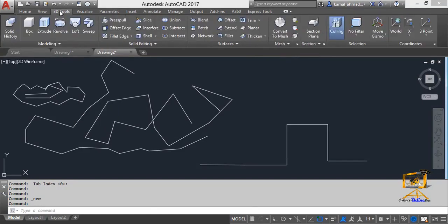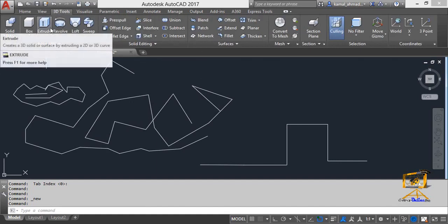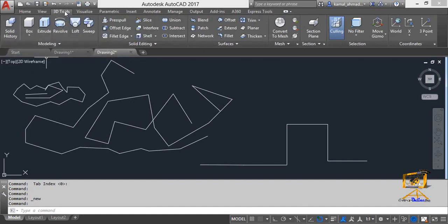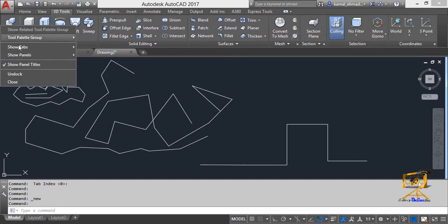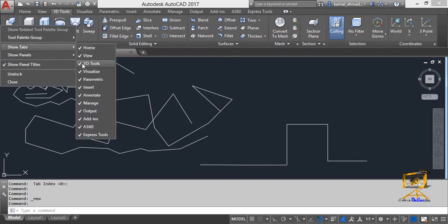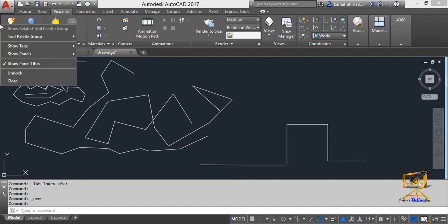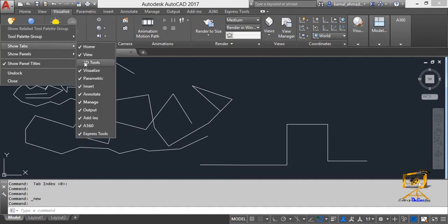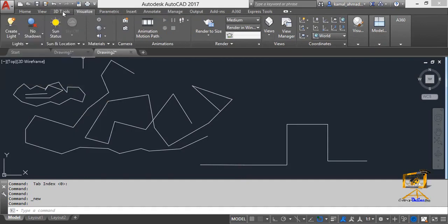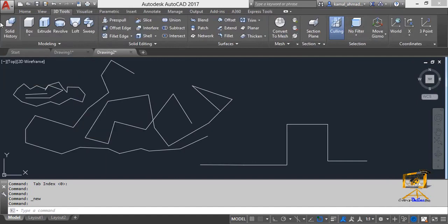As you see here, I use the 3D tab. Click here to see the 3D toolbar in your interface. So how will you enable this tool? You can right-click here, and in Show Tabs on this corner, this checkbox will be unchecked. As I unchecked it here, the tab that was there has become hidden. Similarly, right-click again. I clicked the Show Tabs of 3D Visualization. It came back in front of you.